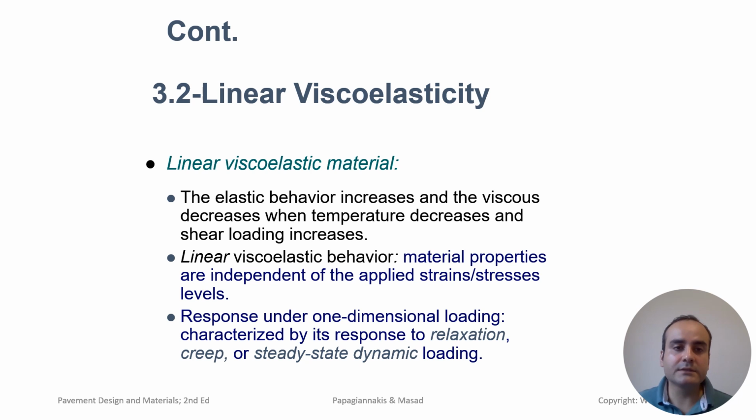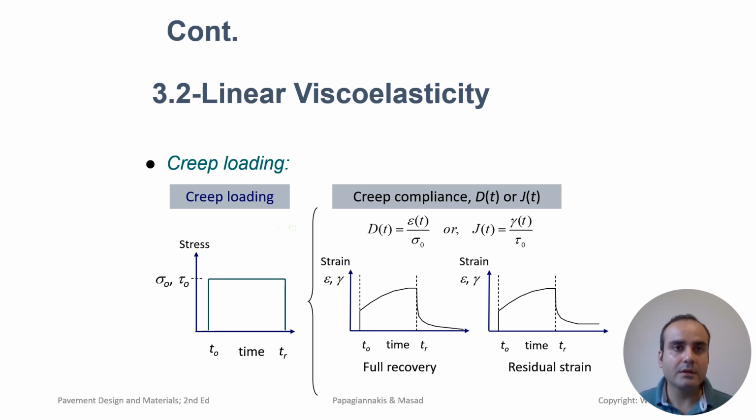In the context of pavement, shear strain becomes significant when vehicles apply loads to the road surface. The way asphalt responds to this stress will determine whether it deforms, as in rutting or permanent deformation, or recovers its shape, which is elastic behavior.